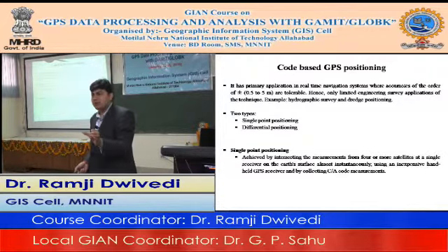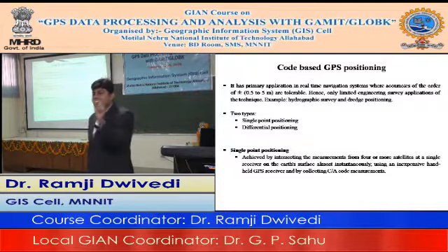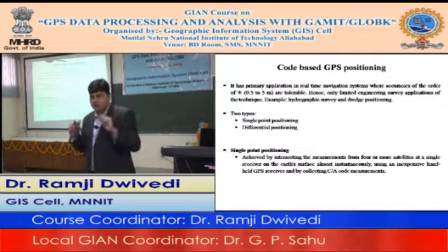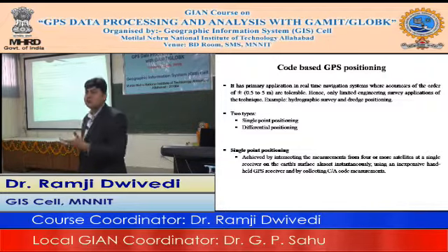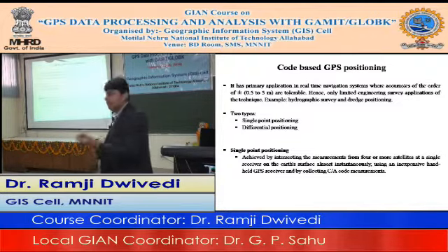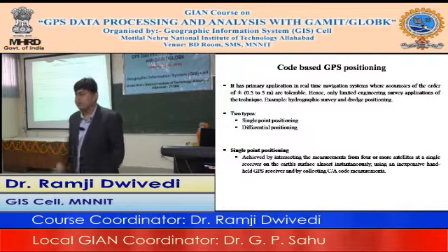It has the capability of taking data correction from the SBAS. The full form of SBAS is satellite based augmentation system. These are additional satellites in geostationary orbits which provide corrections, and that's why we call it an augmentation system. It augments the ongoing satellite navigation systems, which are GPS, GLONASS, Galileo, IRNSS. We have GAGAN also for the Indian continent. So we can achieve this much with code based positioning because of the availability of DGPS real-time corrections, which are available from many sources.